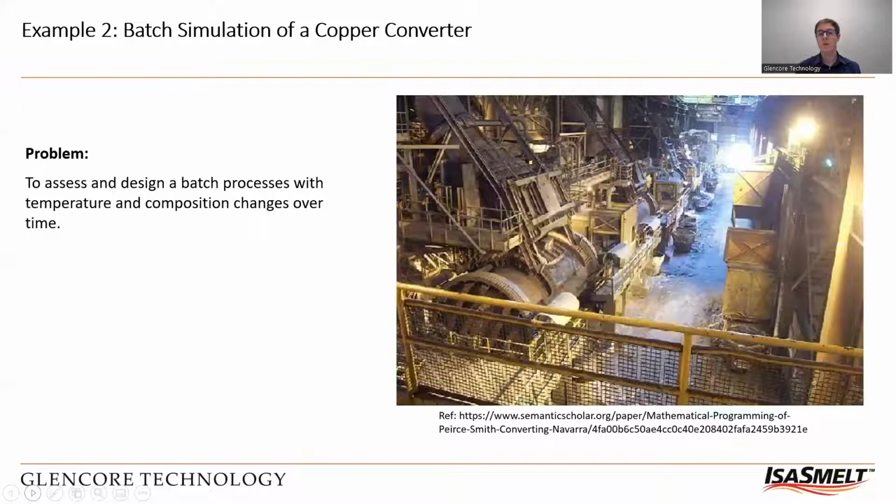So the next one we'll talk about is a batch simulation of a copper converter. Batch simulations are a unique sort of pyrometallurgical calculation. With batch furnaces, we charge materials and do some things, and the composition within the furnace and temperatures within the furnace change over time. And like most furnaces, we want to control our temperature well and control the chemistry really well. But because of the transient nature, things change on a minute-to-minute basis. This makes it very difficult to calculate these really well, and there are very unique calculation solutions here.